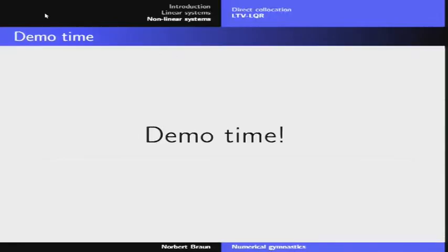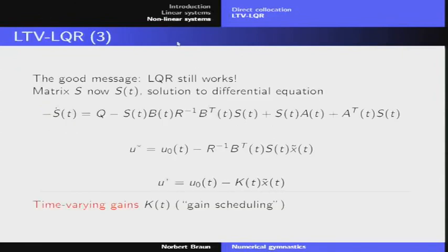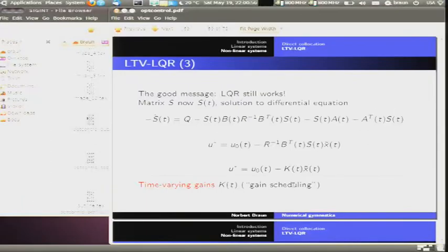Right. So I calculate offline this S of t, but it's just one matrix. It's the same matrix always. Okay. And I measure my disturbance, and I just multiply this. So the last part, the multiplication between this matrix, which I calculated earlier, and the disturbances, this happens online. So I don't need to know how the disturbance will look. I just need to hope that it will be small. If it's large, then I'm dead. Then I can't do anything. But as long as it remains small, and if this works, it will remain small, then the scheme works.